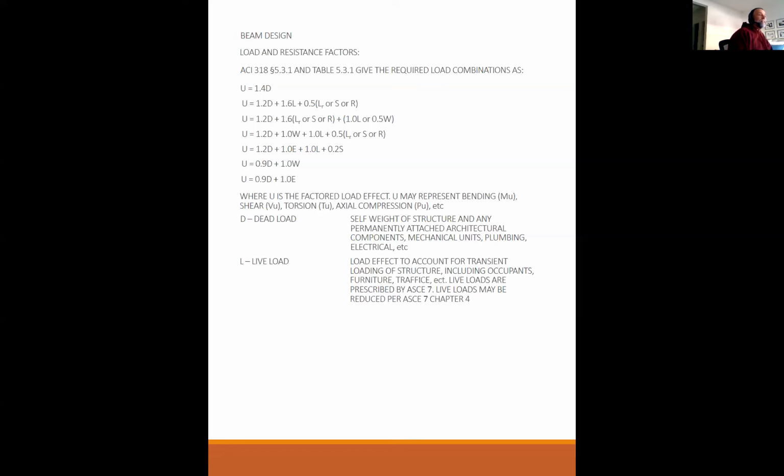And back in the day, we used to reduce that. This live load may be reduced thing. We're able to reduce 50 pounds a square foot down to about 30 pounds a square foot for parking garages. Today, they've changed that to be 40 pounds a square foot unreducible. So that's it, 40 pounds a square foot, that's what you design to.